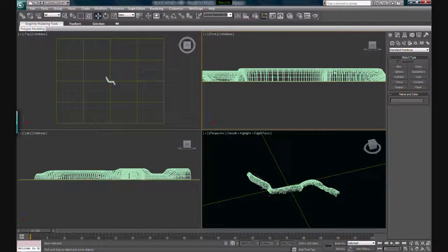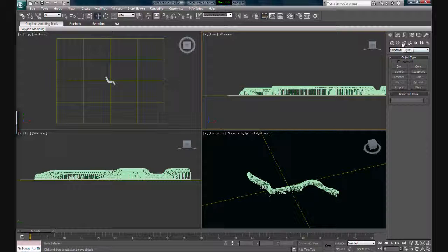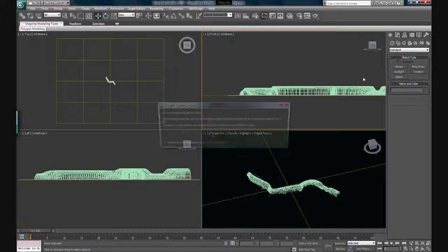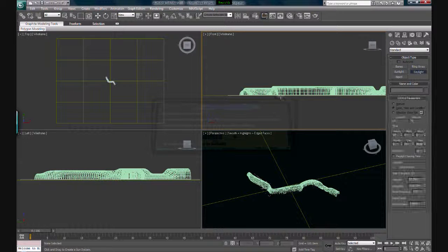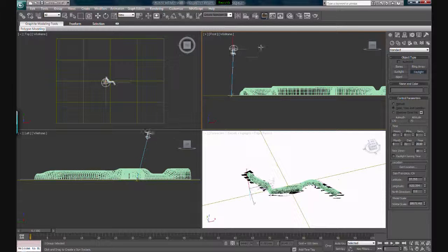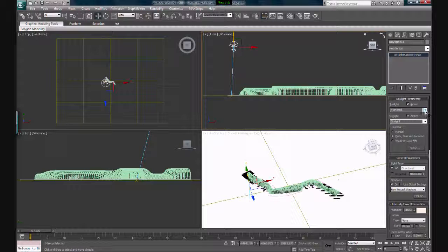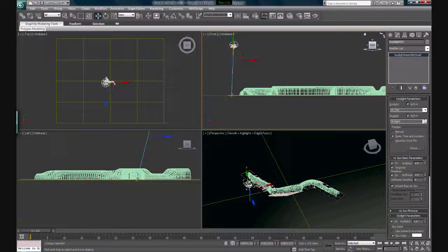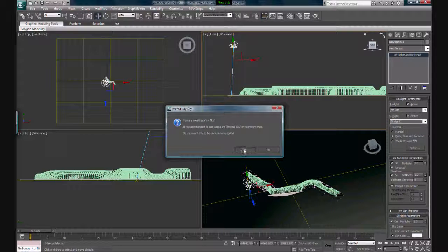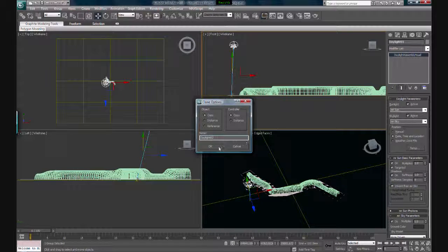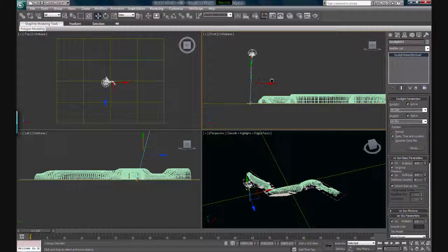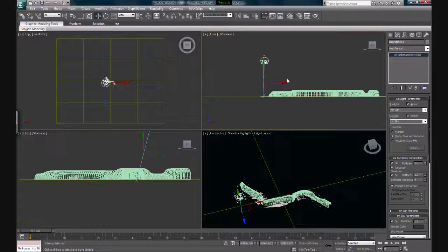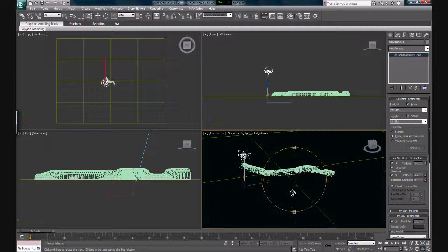And yeah, maybe we could put in some lighting as well. Go to system, daylight, press yes, click somewhere on the ground, hold the sun up, it's fine. Now go to the modify tab, change that to MR sun, and change this to MR sky, press yes. I'm not gonna... oops, sorry, that was accidental. I'm not going to adjust the setting of the date, time and location, just leave it as it is. I just want to render this view, that's all.